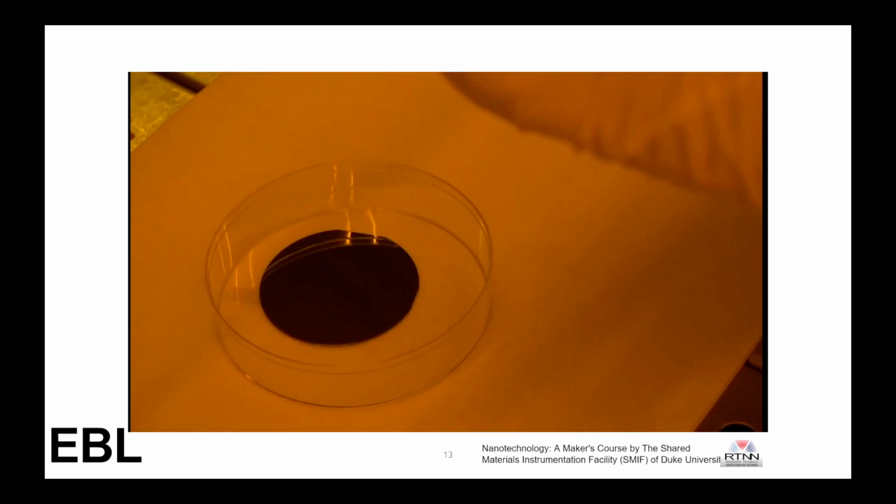Yes. You have to fabricate the sensors so that if you bend them 3 times, 4 times, 10 times, in different diameters, your device will still remain there and keep working. That's why it is flexible. So you use a flexible substrate, whatever the sensing material you use, either organic or inorganic, depending upon use.